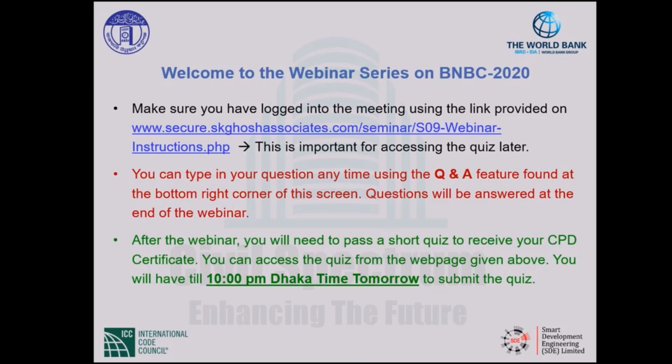Now you go from the second part to the third part at a period T sub L that is called the long period transition period. For the United States, the value of that is 4, 8, 12, or 16 seconds, nothing below 4 seconds. I do not know without checking if in Bangladesh you have a value for T sub L. You will get into the third branch only for very tall buildings, 40 stories and higher, or very long span bridges. So most of the time we do not deal with T sub L or the third branch.